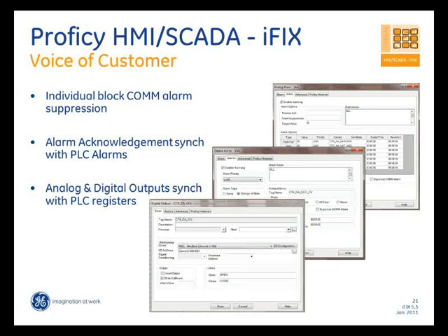And quickly getting into some of the VOC updates. One is on our analog alarm and our digital alarm blocks. We modified the way it treats the contact tag names. So you use analog alarms and digital alarms, and your contact tag name is actually a bit in the PLC where it also informs the PLC of alarm acknowledgements. What we have done is that particular field, when an iFix database starts up, is synced with the PLC register that you see, or if there is a COM failure between iFix and the PLC and it comes back up, before anything being written out, it is first synced.